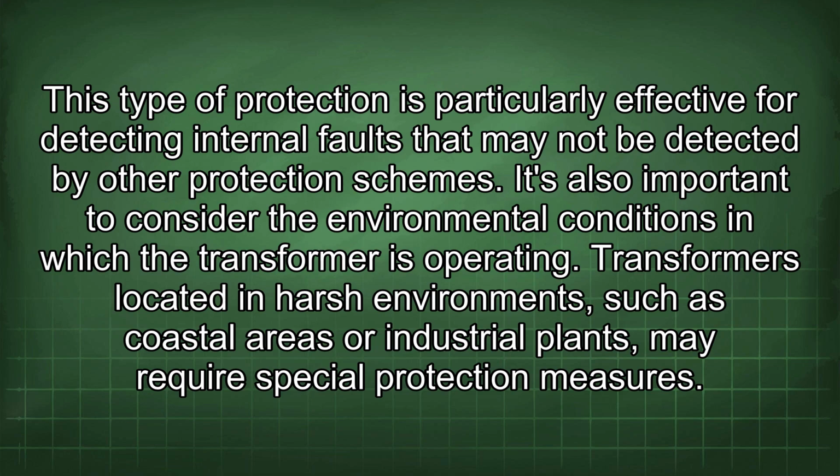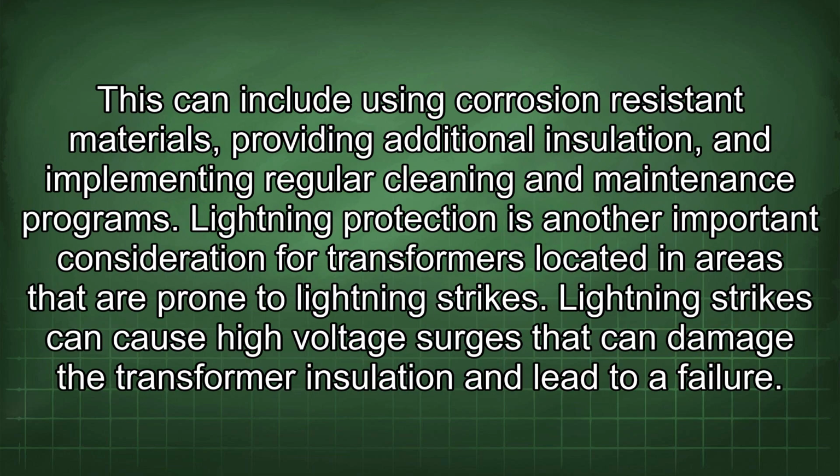It's also important to consider the environmental conditions in which the transformer is operating. Transformers located in harsh environments, such as coastal areas or industrial plants, may require special protection measures. This can include using corrosion-resistant materials, providing additional insulation, and implementing regular cleaning and maintenance programs.